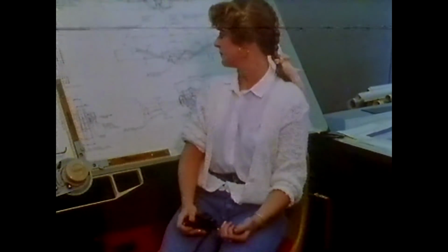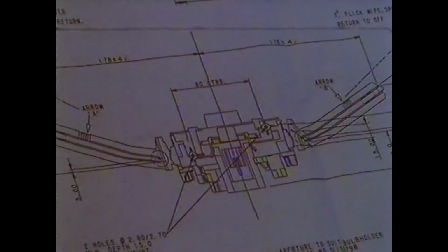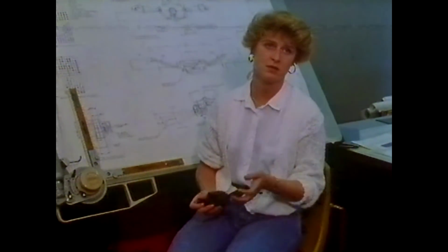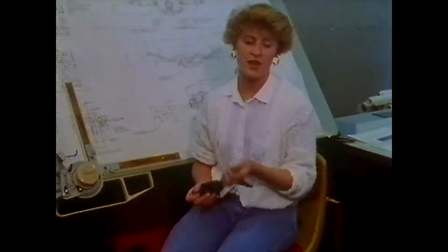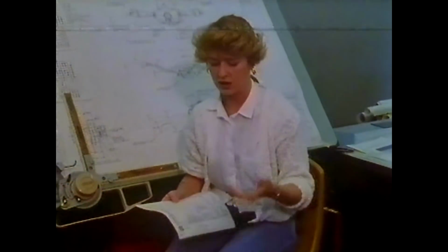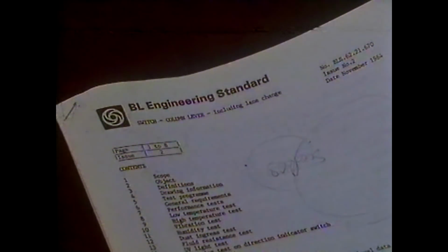Here in the design office, we design switches, and the first piece of information we get is a customer drawing. We can tell from the customer drawing what they actually want the switch to do, whether it's headlamp, wiper, whatever, the various positions of the switch. And then we use the customer specification, which tells us the product life, what sort of high temperatures, low temperatures it has to stand, vibrations, humidity. We design a switch to the car manufacturer's requirements and also design it so that we can build it here in our factory.